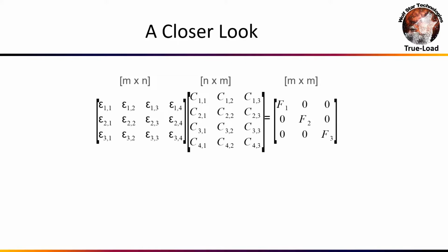This is great. So let's talk about these unit loads a little bit here. These unit loads could be anything. These could be forces, these could be moments, they could be unit displacements, they could be temperatures, pressures, inertia loads, they could even be mode shapes. So if you laid strain gauges based on mode shapes, TrueLoad will directly calculate the modal participation factors for those mode shapes. So that's pretty fantastic. But we can take that a step further.